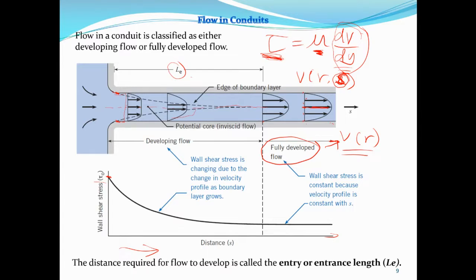And for the mass flow rate to be maintained, the particles in the middle have to move faster so that the mass flow rate at any given point in time is constant, because there is no accumulation, there is continuity. Okay, the continuity equation plays a role. There is no accumulation. That is why the particles in the middle now move at a faster rate than those close to the walls to maintain the same flow rate.